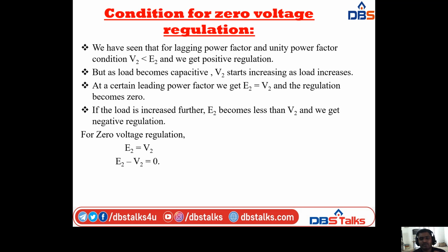Up to now it is lagging and unity, but as the load becomes capacitive, V2 starts increasing. That is, V2 is greater than E2. V2 starts increasing as the load increases. So at a certain leading power factor, we get E2 equal to V2, and the regulation becomes zero.